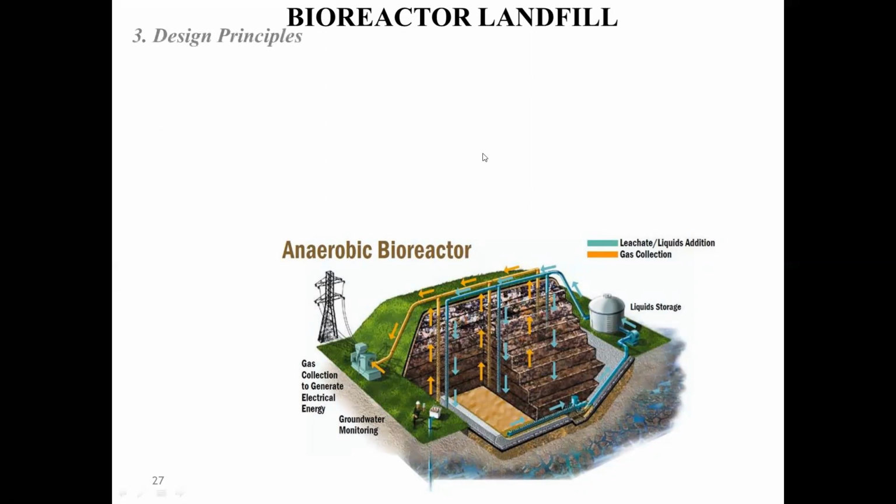Okay. So what we do in this one is accelerate the biological decomposition process of the organic fraction. By putting in water, the waste is going to get broken down, and the speed at which the decomposition takes place is going to increase. That is going to be speeded up, because of which the acceleration is done in our bioreactor landfills.